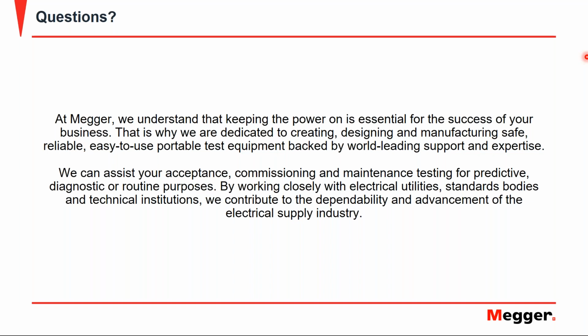We can evaluate the quality of the workmanship or installation of a cable. We'll also be able to see if a bend radius was exceeded when the cable was installed, or if there's any type of separation within the cable that created a void that's creating partial discharge. But also, like Charles mentioned during his presentation, we can use partial discharge measurements for maintenance purposes to evaluate service aged cables. As far as the question goes, this method can be applied to all types of cable insulation mediums.